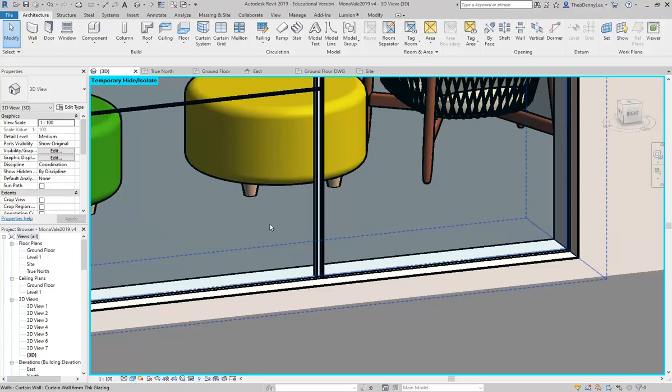and things like that, sometimes it's your only option. And it can give you an idea how thin glass can be when you see that really thin, 3 or 4 mil old glass. But for newer glass, in newer windows, it should be at least 6 or 7 mil thick. It's 6 point something in reality. If you talk to the glass makers, 6.7 or something like that, and they will go down to the fraction of a millimetre. They're that accurate. And it goes up to not much more than 10 for the glass that they use in things like windows.